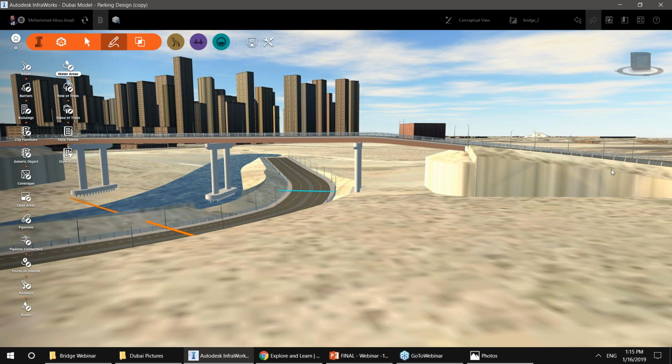Can you use Infraworks without using Civil 3D to finish a civil project? Well, this is a great question. Infraworks is very powerful, as I mentioned, for the planning of infrastructure projects, for creating the conceptual and preliminary design, and a little bit of detailed design. But inside the Infraworks platform, we cannot generate the final quantities, and we cannot generate any construction documentation whatsoever. No cross-sections, no plans, no profiles at all. So Infraworks cannot replace Civil 3D for that purpose.